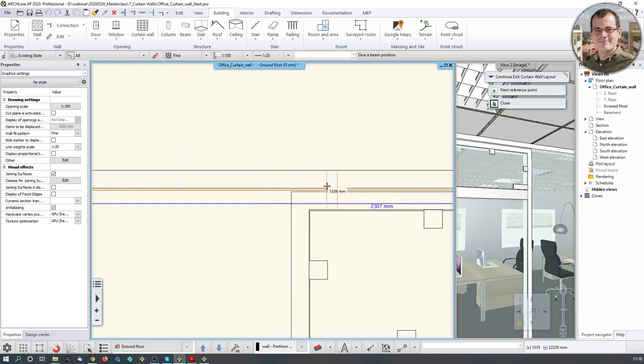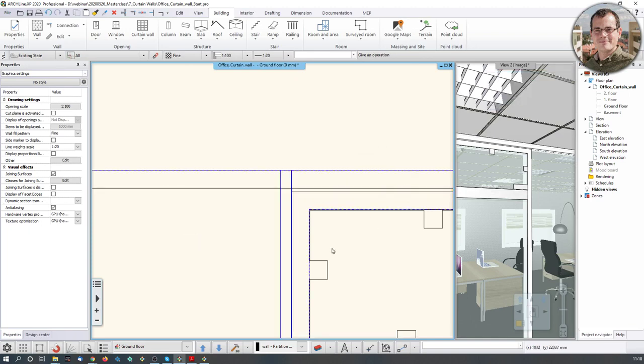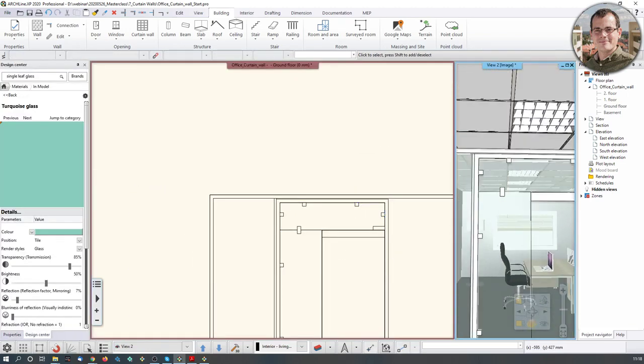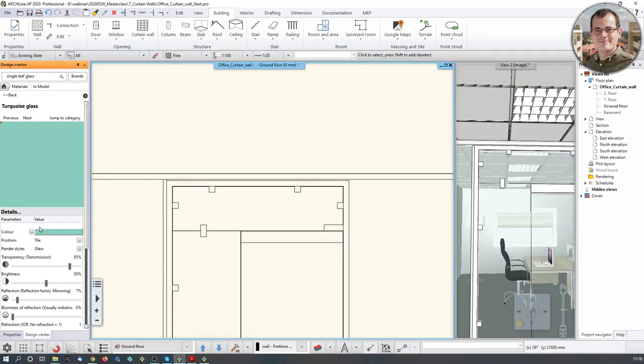By the way, when you are positioning something, you see that the cursor is on the left hand side and the mullion to be moved on the right hand side. But if you want to flip it, because this is your reference point, but you want the mullion to move here, you just hit the F5 key or just toggle it over here, and then if you click, the division would be at the right place like that. So now I have moved the improper division to somewhere else.